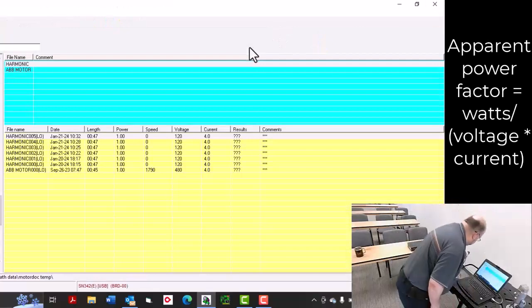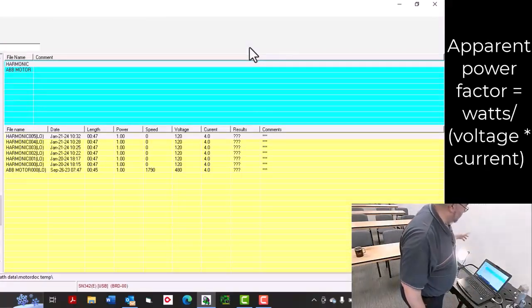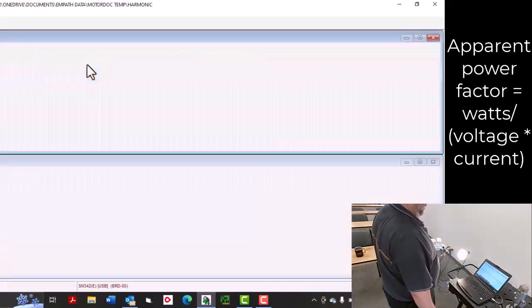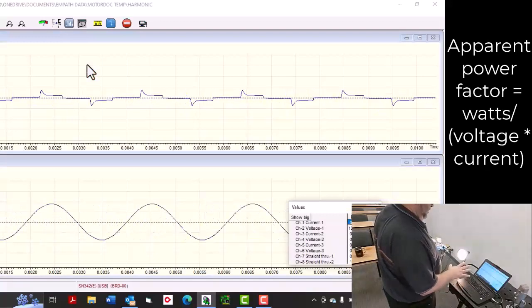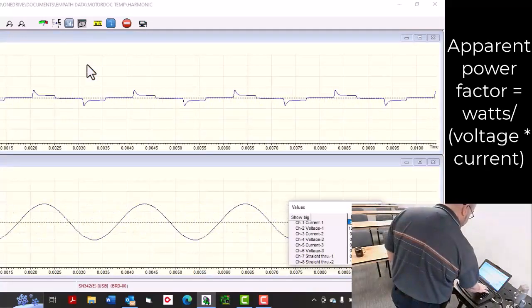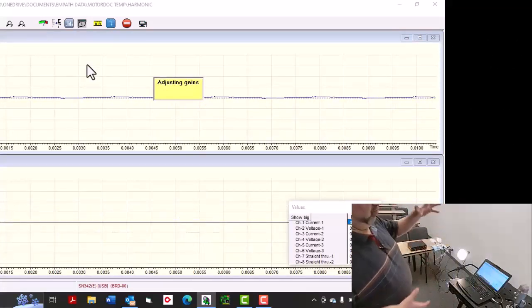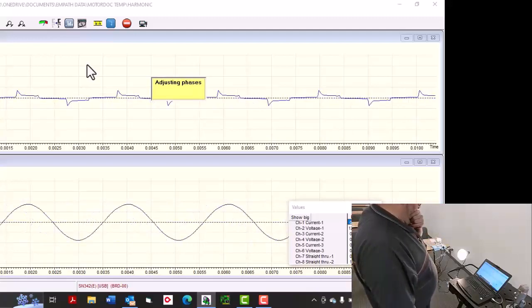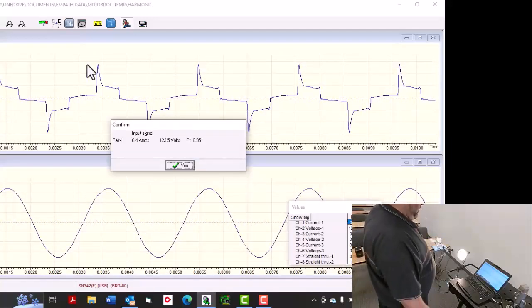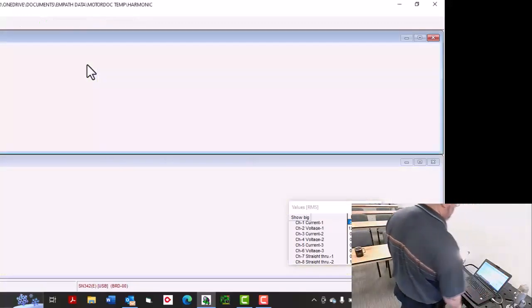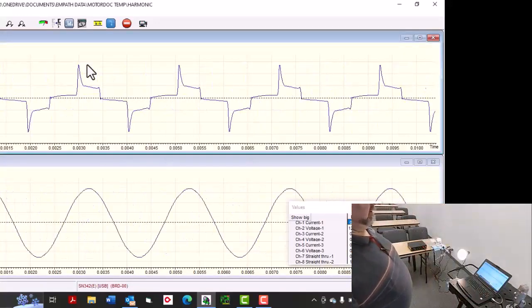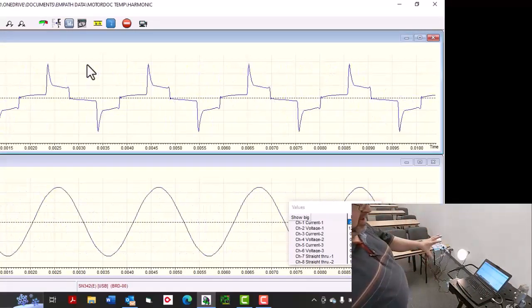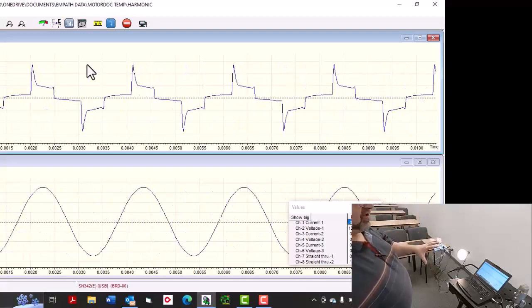We are going to repeat our prior experiment, and we're going to add 10 LED bulbs in effect. Okay, now you can see this popping up a little bit, and we'll get it more into scope here. Okay, power factor, a little improved. But you can see these peaks are very defined, and that notching, that is what happens with an LED system. It's not a sine wave anymore.